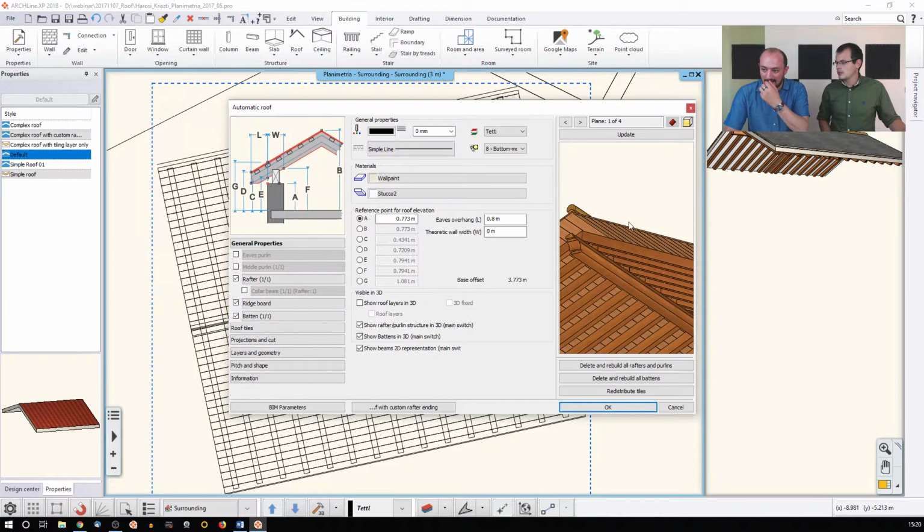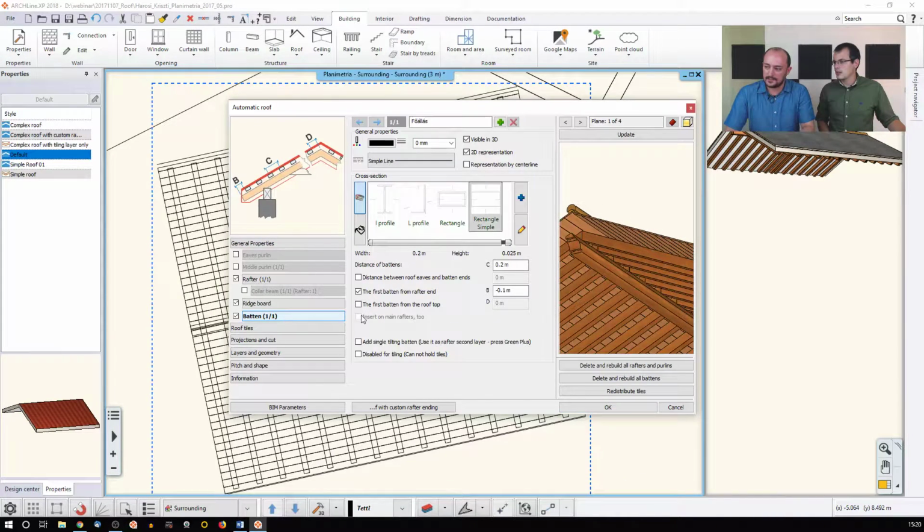And this actually is made out of battens by simply changing their widths and heights and just using the same frequency for the distance of battens as the width of the battens, and then this makes like a planking or something like that. So this way, actually, you can also build up another batten on top of this, which really literally works as a batten, holding the tiling, which I will talk about soon. And then you can just build up a way more complex roof structure using this same simple method. Or you could use this method to cover the rafters from below, right?